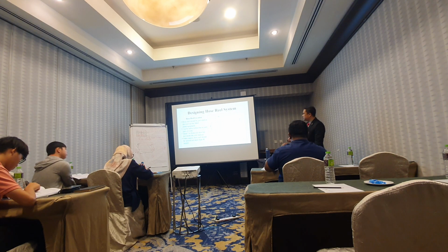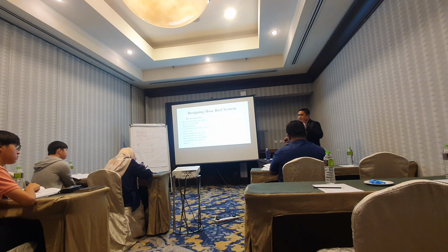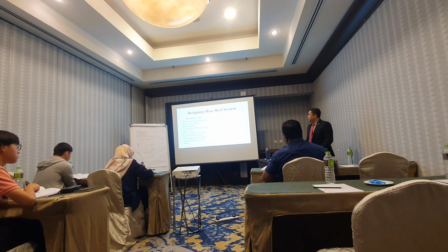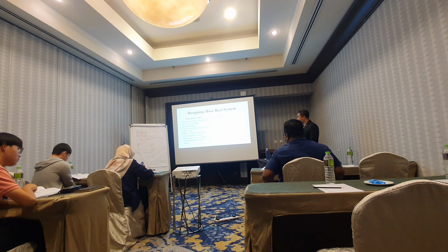This is the second requirement. Sited 5 meter from exit door, but not inside the exit staircase. Dia tak boleh inside exit staircase lah. You cannot put the hose reel inside the staircase. It must be outside the staircase. Yang can inside the staircase is for bomba nanti lah. Open spaces hose reel should be spaced not more than 48 meters. This is the requirement lah.